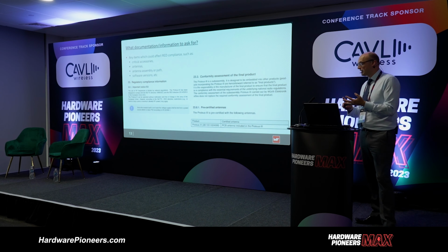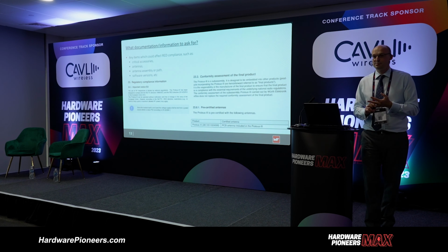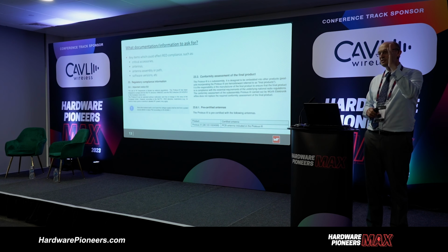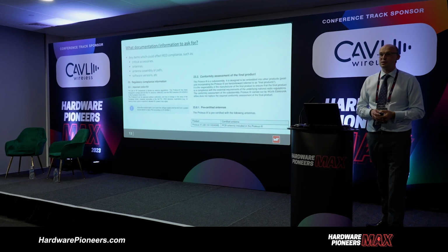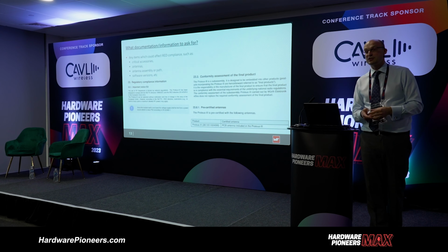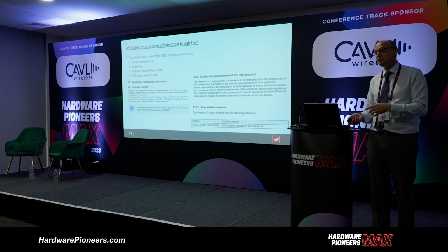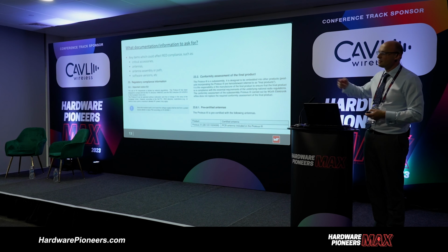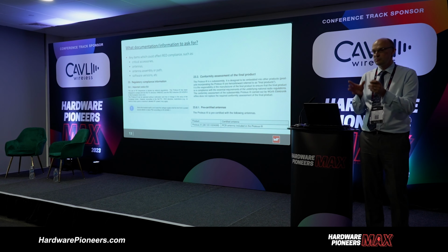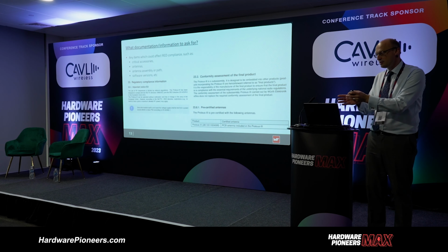If we do, there is a problem, because you can now actually allocate a channel within a certain band. Unfortunately, that does not meet the essential requirements of the Radio Equipment Directive, the Radio Equipment Regulations, because it's not effective use of the RF spectrum. So little changes to firmware can have an impact on your pre-approved radio module, either as a standalone device or once it's embedded into your end product.